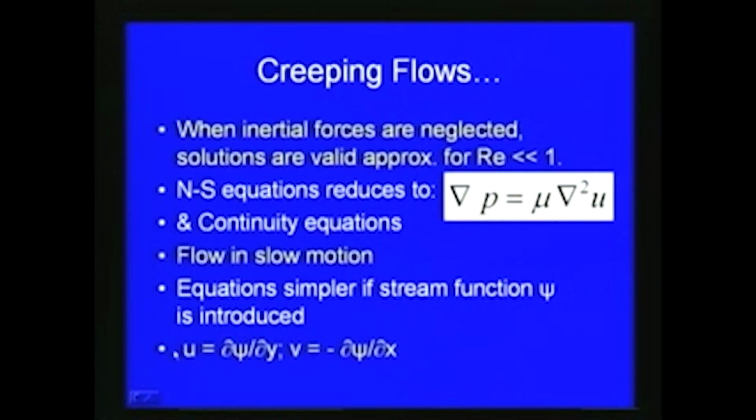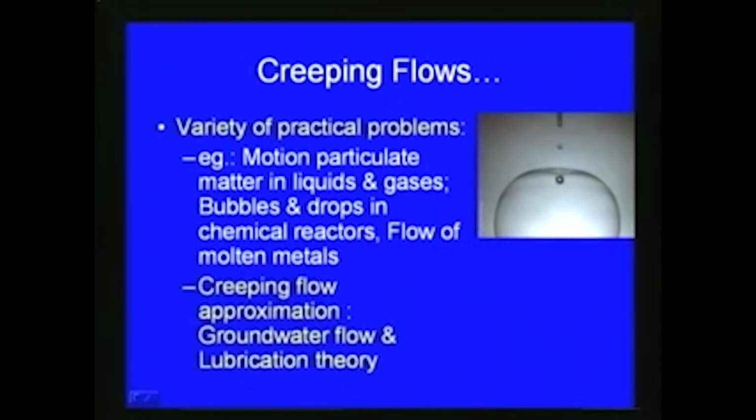And here, if we use the stream function instead of head or velocity, the equations will be simpler if the stream function psi is introduced. So, we can represent u is equal to del psi by del y and v is equal to minus del psi by del x like this, and then we can rewrite the governing equations starting from the Navier-Stokes equation, and then try to solve the problems like what we discussed in the case of creeping flows. A number of problems can be solved in this category of creeping flows.